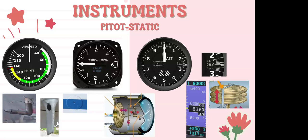Now, why would we want that? Well, it's an altimeter. We want it to know when we're at essentially mean sea level, 0 feet, right? Because that's how we're going to get our mean sea level for every other altitude that we're climbing to. I was going to say or descending to, but hopefully you're not descending below 0 feet. So inside there, we have that sealed 29.92. Now, like the other instruments, we also have a line going to the case from our static port.